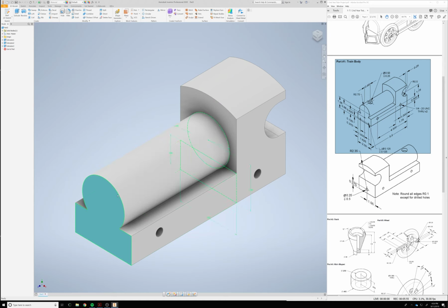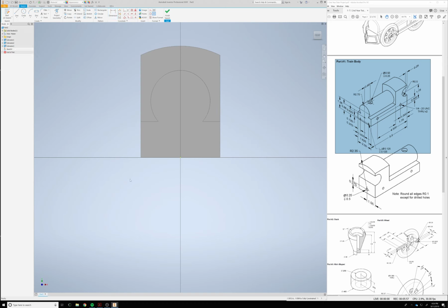Alright, almost done. I'm going to click on this front face. I'm going to hit S on my keyboard, and that creates a new sketch. And I'm going to place 3 holes. They're all going to be different random sizes, so I'm going to use my equals constraint to make them all the same size. I'm going to use my horizontal constraint to lock this and this center together. And then I'm also going to use my vertical constraint to lock that vertically in line with the origin.